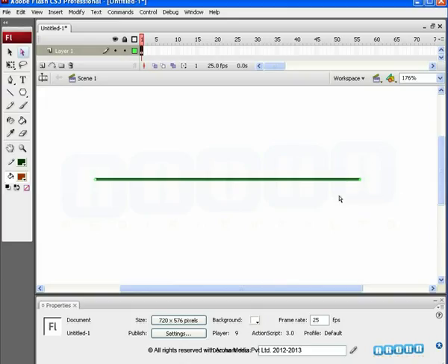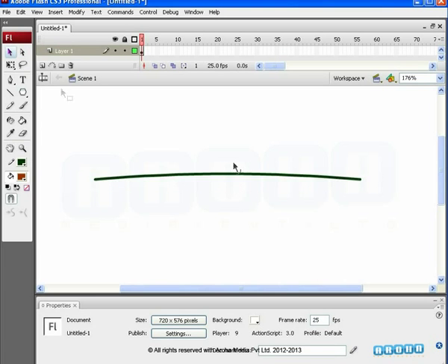There is one pointer worth mentioning here. If you use the Sub-Selection tool on a straight line, your handles and nodes fall on the same line, and it gets a bit difficult to find the ends of the handles. There's a solution to this. Curve the line just a little bit before you start using the Sub-Selection tool. See how the handles are clearly visible now?